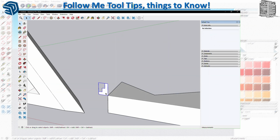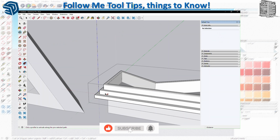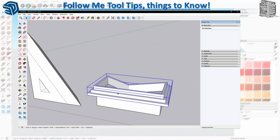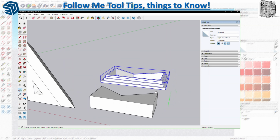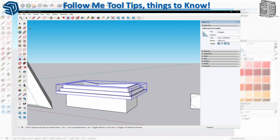And then when I have the group, select the surface, go to the Follow Me tool, on the group go to edit, and then select the surface, and it'll basically create an object. And the good thing is the object is still grouped, so you can move it to the side, and it's not attached to it. It's going to be really helpful when you are drawing a building, doing your logistics.